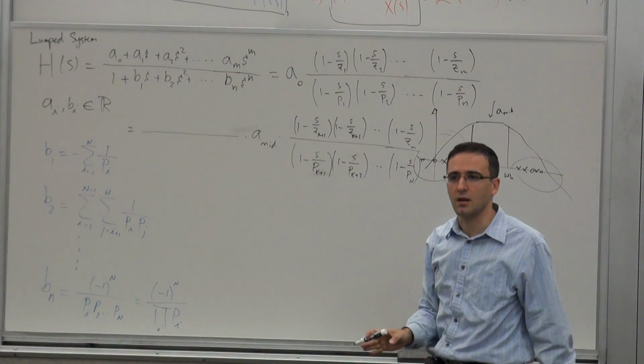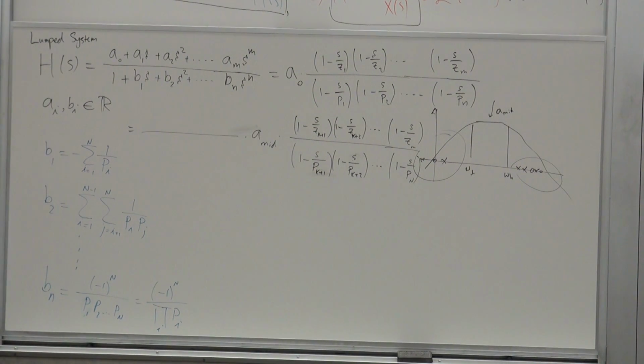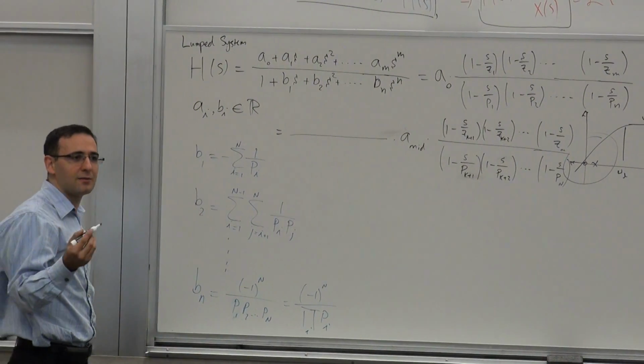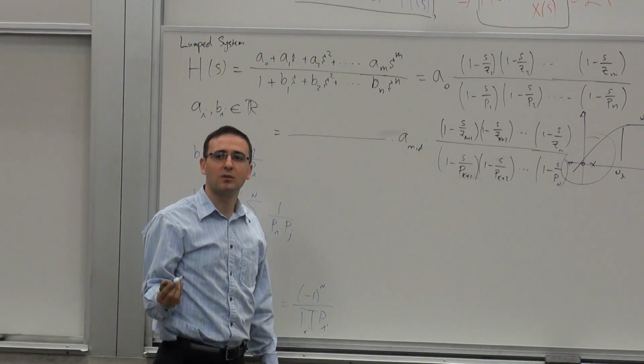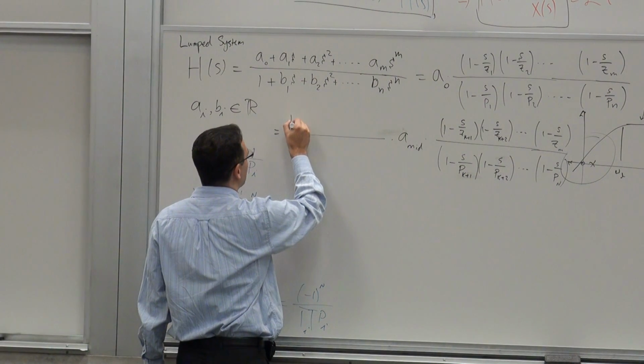How about the low frequency stuff? Now, we can write them in a better form, actually, the low frequency stuff, which is the form that was called by the late Professor Middlebrook the inverse poles and inverse zeros. So this is basically the way you would write it.